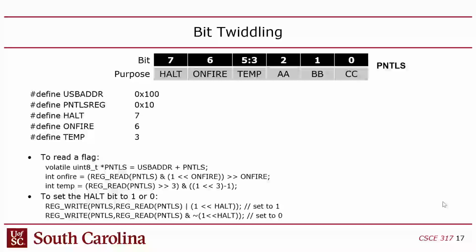in this case, I have the peripheral address, or the starting address of the peripheral. This is the base address at 100. You guys with me? This is where the addresses start for that peripheral. And I've set them up as a define. And then I have an offset. So this offset is how many bytes after that starting address of this specific control register I want, right?